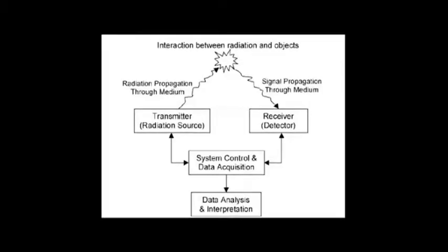One of the fundamental aspects of remote sensing is that you're able to obtain information about an object without the sensor being in direct contact with the object. However, remote sensing still requires some kind of interaction between the target and the sensor in order to acquire information. The interaction between radiation and the object can be explained with the LiDAR equation, which relates received optical energy, or the photons received, to the transmitted optical energy.